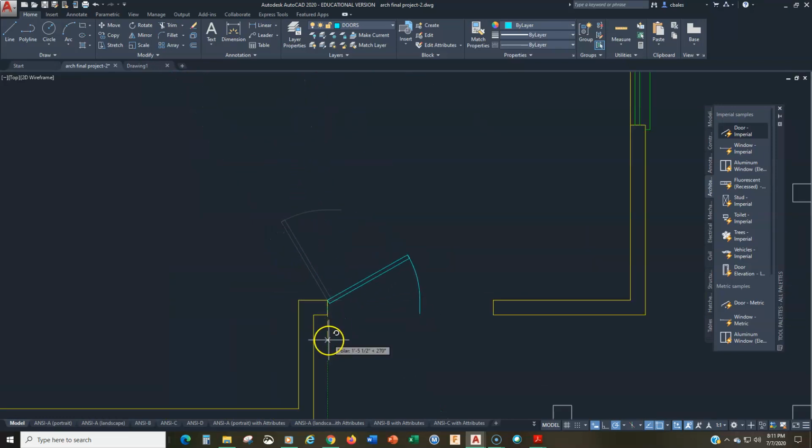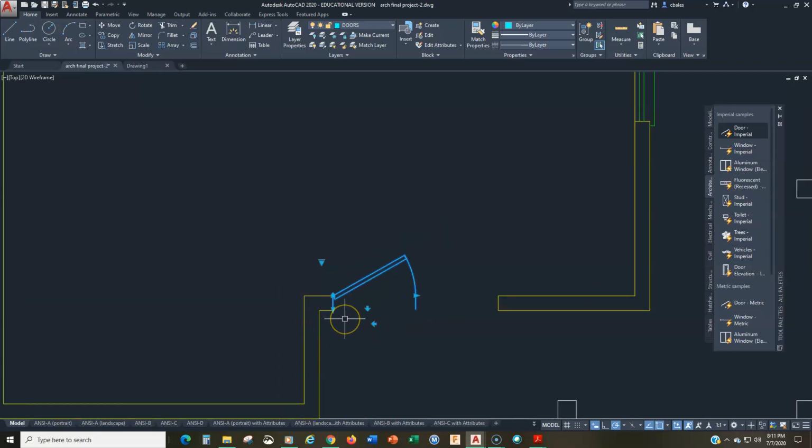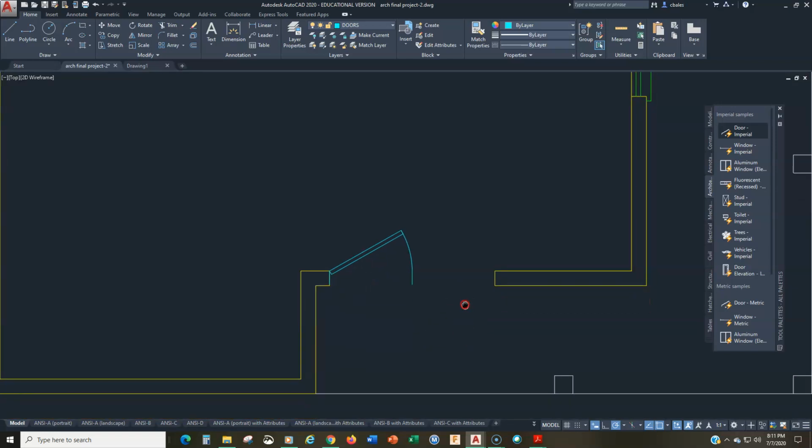And we're going to go like this. This is a 3-foot door, 3'4", so I'm going to go back to 3 feet. Everything else is fine. And then I want to finish this off by drawing a line. Now watch, I'm going to draw a line from the midpoint here on the door layer to right there, right? That's kind of exactly what it shows in the drawing.